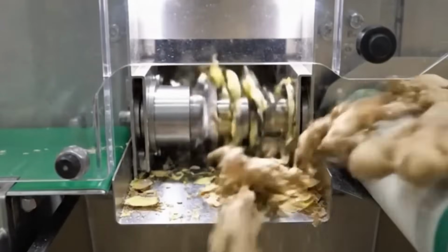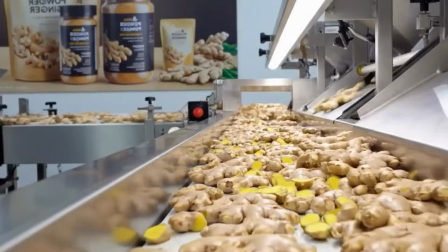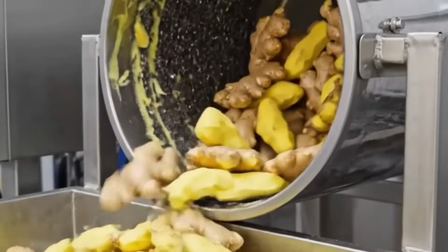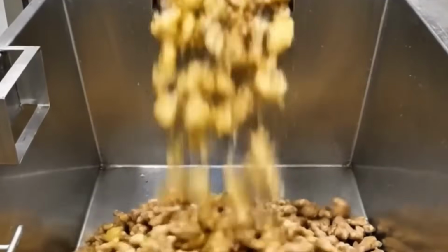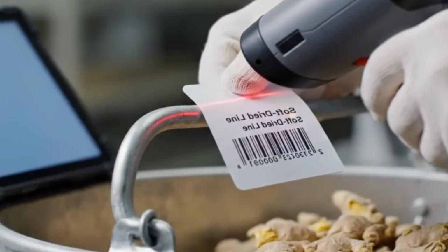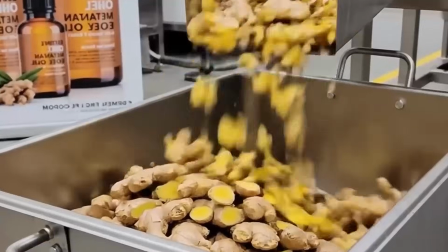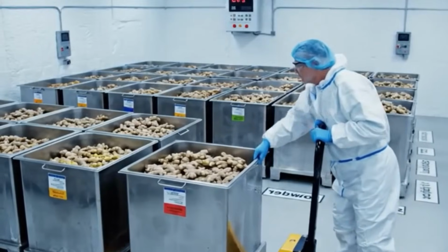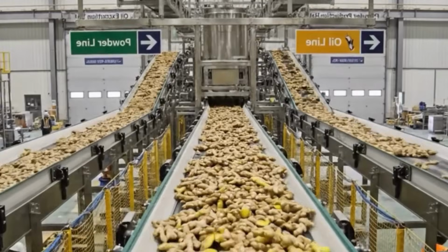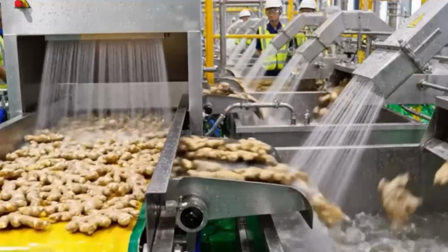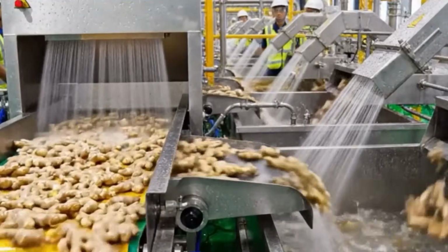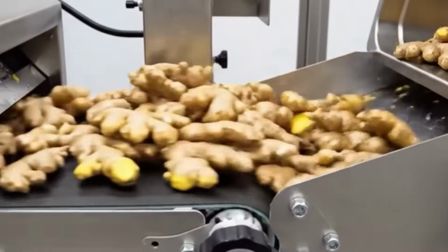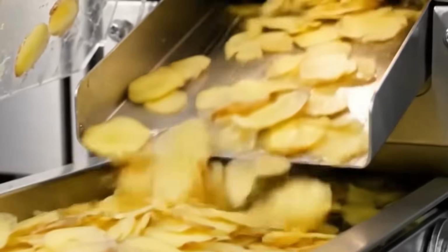These vessels are jacketed for thermal regulation and include bottom-mounted mixers driven by variable frequency motors to achieve high shear mixing. Ginger extract, lime oil, lemon oil, and proprietary spice emulsions are stored in temperature-controlled dosing cabinets and delivered via sealed piping to the blending tanks. Dosage is governed by recipe management software, with peristaltic pumps calibrated for microdosing accuracy.